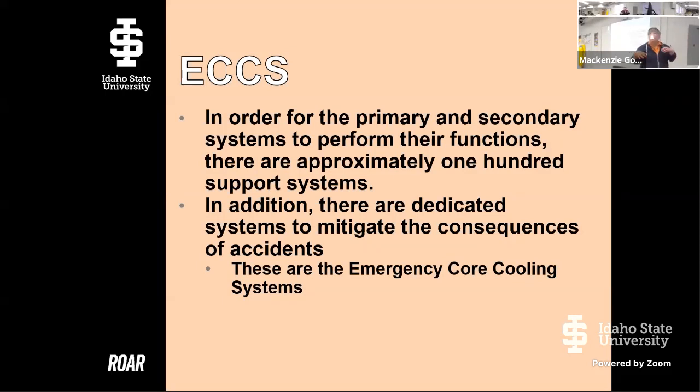So it falls into a lot of odd categories of having to be very highly maintained, but then we have some system issues where it isn't actually activated very often, right? So how do we prevent valves from getting stuck or pumps from getting corroded and not turning on as efficiently as they need to when we don't really use this system? One of the answers is we're going to test it regularly, but it's a unique system engineering problem, which means it's a unique operations problem for you guys to be part of that maintenance and testing.